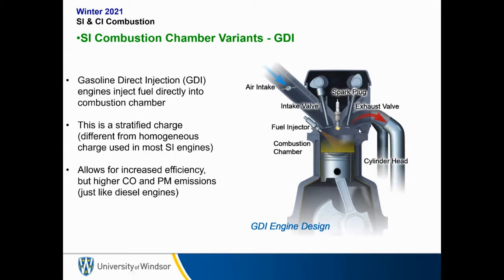Now, we've talked about the importance of mixing the fuel and air and how most of the time the fuel and air is mixed before it gets into the cylinder. Well, to be honest, almost all modern gasoline or spark ignition engines, particularly ones that you would buy after about 2020, so in other words, any new vehicle nowadays, are not going to use injectors in the intake manifold anymore.